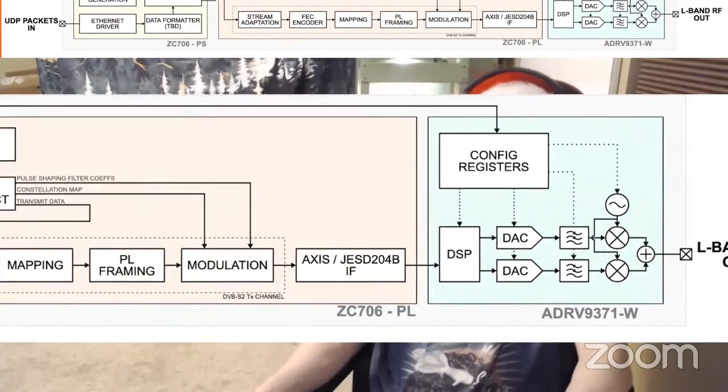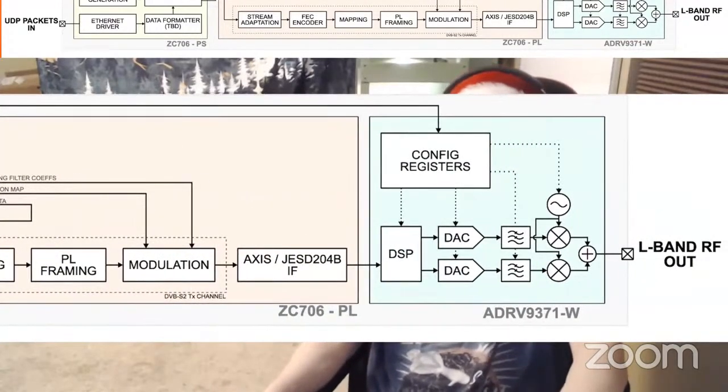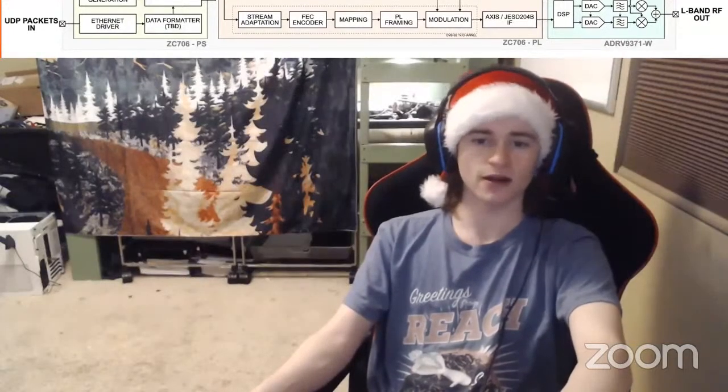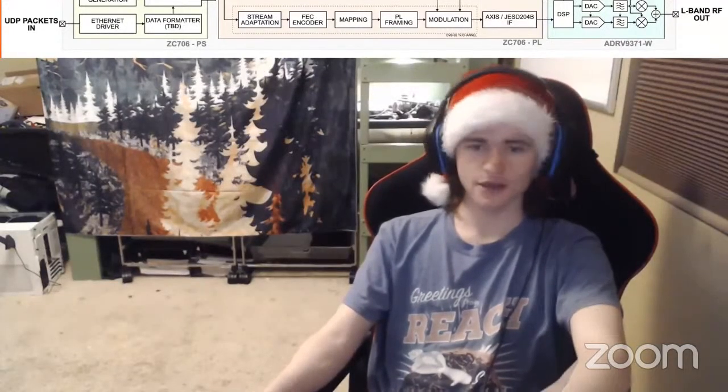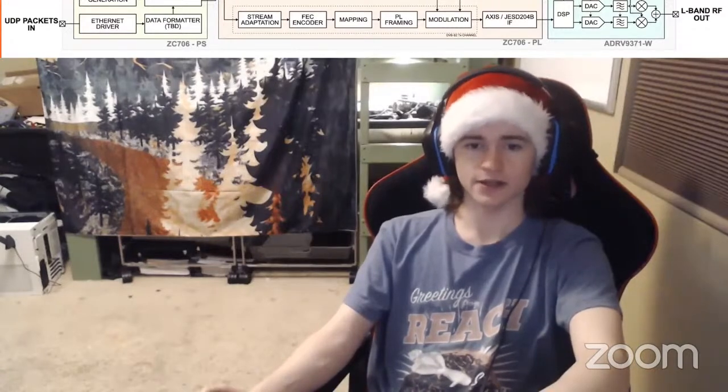The radio chip is from Analog Devices. We use the AD9361. We connect the radio chip with a high-speed interface. The languages for the FPGA design are Verilog and VHDL. These are computer languages that describe digital hardware circuits with software commands. When you compile this code and move it into an FPGA, the FPGA is physically reconfigured. Need to make changes? Load a different combination.